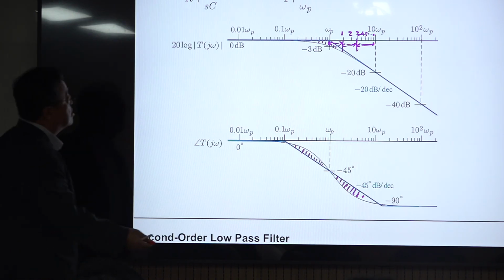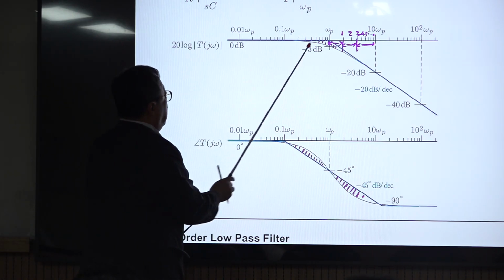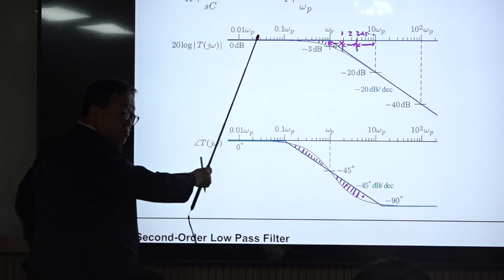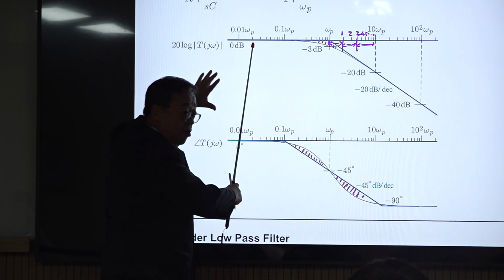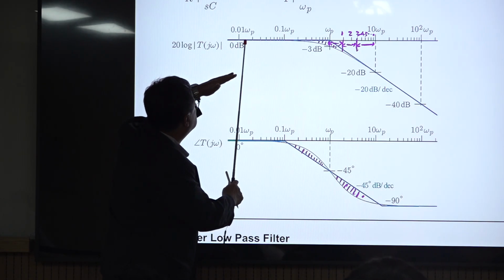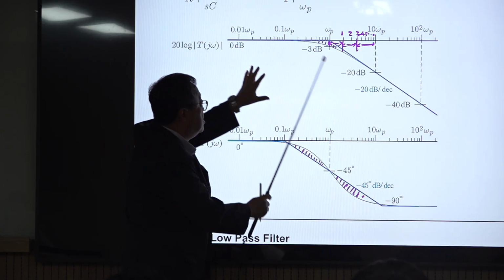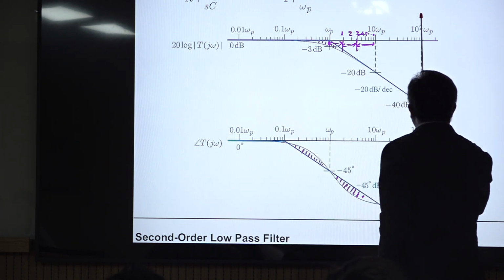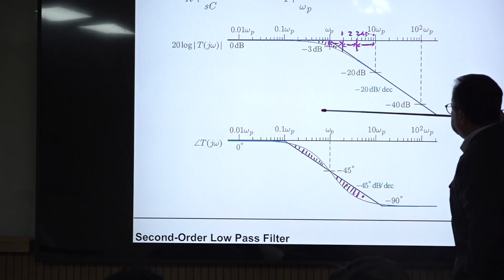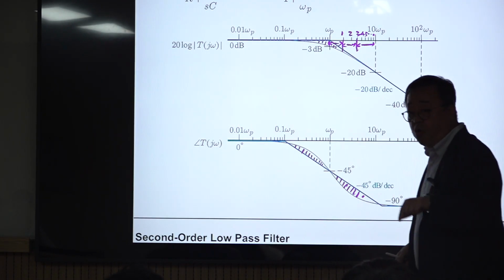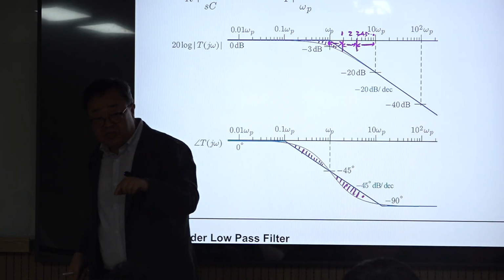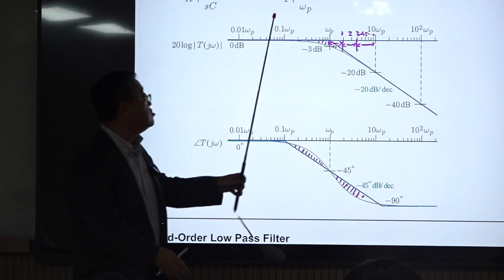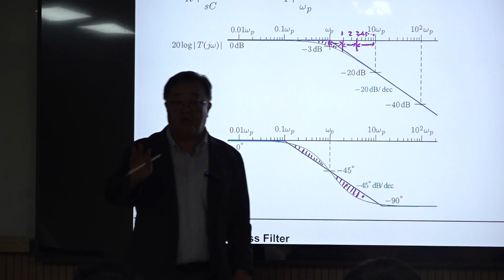If you take a look at this, the sinusoidal waveform is here, then it passes not attenuated, untouched in magnitude, because this is 0 dB, but this high frequency sinusoid waveform is applied here, then it will be attenuated by minus 40 dB, which is 0.01 in linear scale. So high frequency component is way attenuated, and the low frequency component is passing unattenuated.